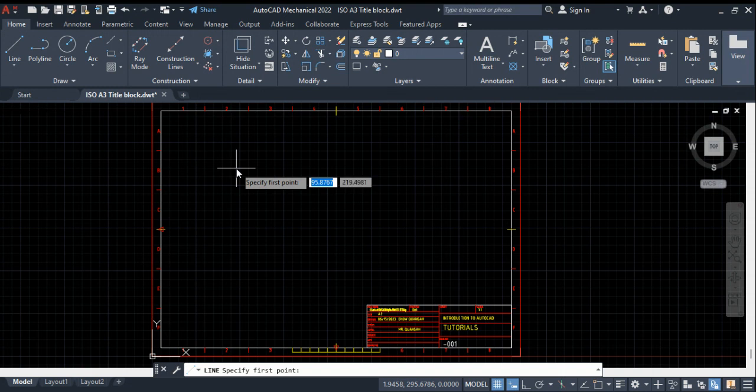This time round, I don't want to just draw a line, but I want to draw a line of a specific length. So if you're not seeing the insertion point or the dynamic input coming along with the plus sign, it's a sign that your dynamic input is off. So if I click down here, the dynamic input, you realize that it goes off. I only have the plus, the cursor. So I click, it comes on. I click, it goes off. So take note of that. In case you can't see yours, just locate it.